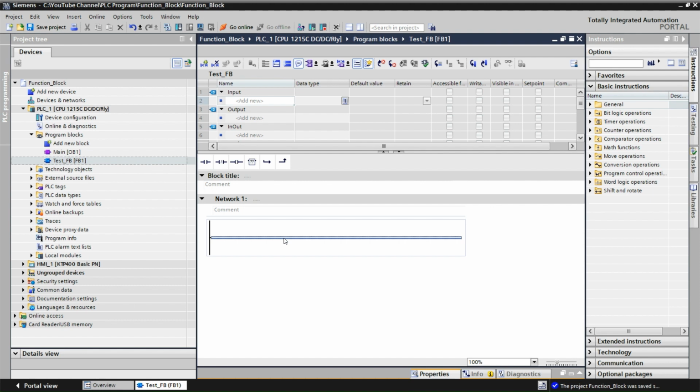In your automation project, if you are using a temperature sensor, pressure sensor, level sensor, and motor breaker, for all of these you need to create an alarm in case there is an abnormality. Like if the temperature goes high, it triggers the alarm. Same with a level sensor, if there is a high level, then you need to trigger the alarm. So it will be linked with the function block. So we will create an alarm control block, then we can link it with the sensors.